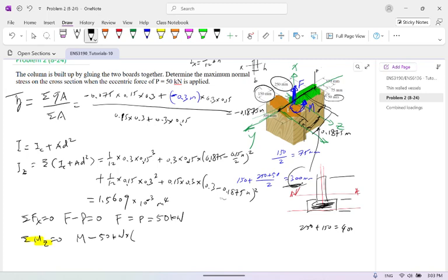Okay. But remember the whole thing should minus the neutral axis. So that's why here we can work out 0.4 minus 0.1875. So it's a meter equal to 0. So we can work out M is equal to 10.6256 kilonewton meter. So that's why from here we can get this idea, we can work out. So that's for M. So remember, we can only get all the internal force. Could have a normal stress in compression, and also there's one moment for this structure.